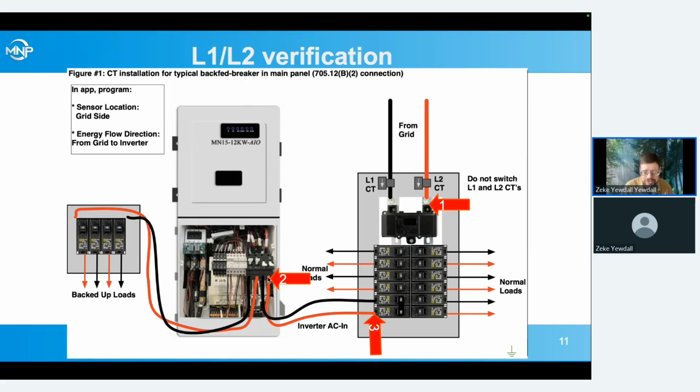So you might have to measure in a couple stages rather than just measuring directly, but make sure that you've got your phase 1 and 2, and in three-phase systems, you've got to make sure all 3 phases are correct. Otherwise, the inverter's all confused and doesn't know whether to turn right or left if you switch those two CTs.